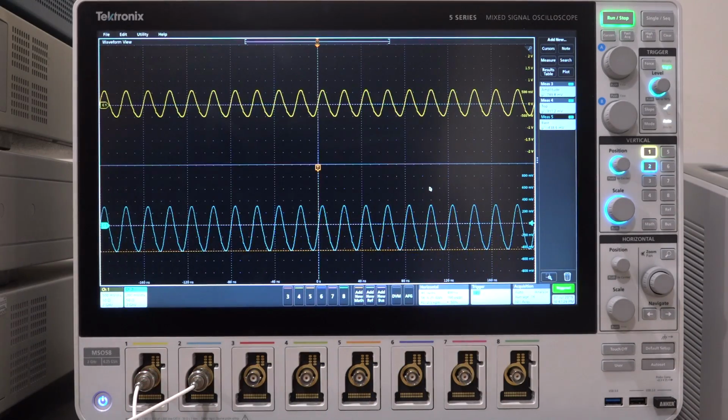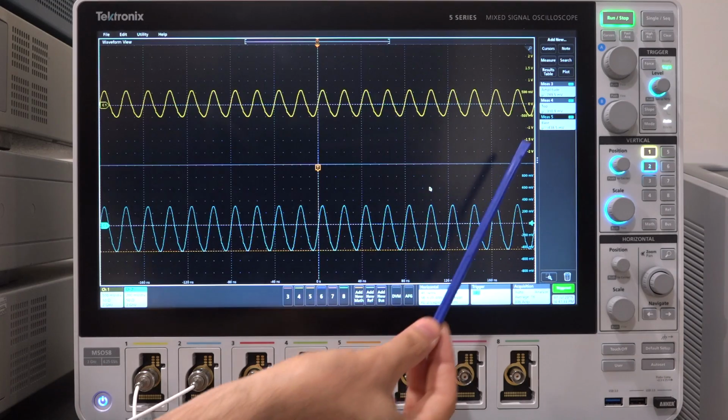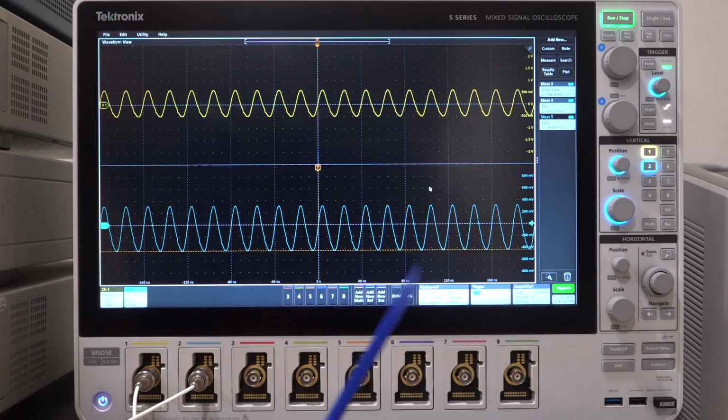Once again, we have a much more sinusoidal response. We do have a slight asymmetry between the top and the bottom. You can see that the top is 311, the bottom is 436 millivolt. That's exactly what InstaView also told us, that there's an asymmetry in the signal there as well. There you go. You can see that it works, and in fact you get a fairly good idea of what's being applied to the DUT.